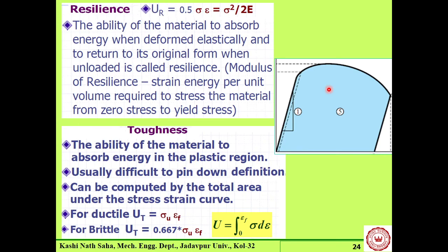That's fine. Then there is the measure of toughness, which is a measure of the energy it can absorb before failure, you can say. And there is another measure which is known as resilience. So what is the difference between toughness and resilience? Toughness is energy absorbing capacity up to fracture, and resilience is the same capacity, but up to the elastic limit. That is also known to you.